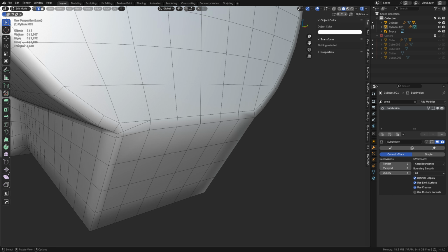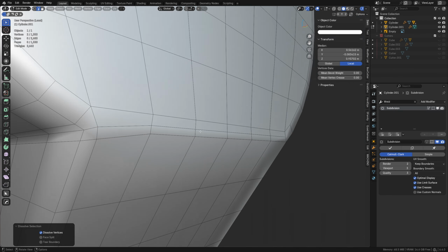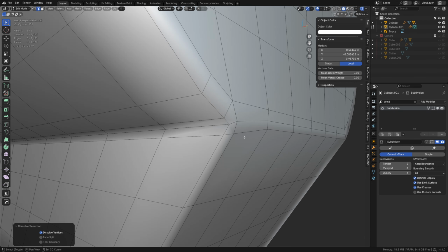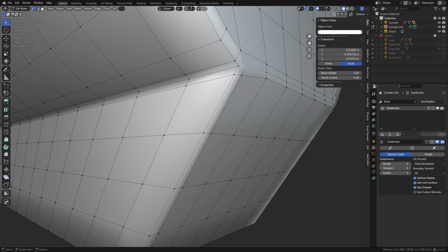As you do more subdivision modeling, you're going to realize it's really cool what you can get away with when you start focusing on a couple things. Setting up the basic forms and shapes you need first, figuring out how to do redirects. So redirects are really just like creating end poles for the most part. It's like subdividing a triangle or cutting a quarter of an inset. This is a redirect, basically, a quarter of an inset. So we can do that all day long, if we had an edge coming up from the bottom here. And those same things are used to increase resolution or decrease resolution, basically. So you can imagine we wanted to decrease resolution in here.